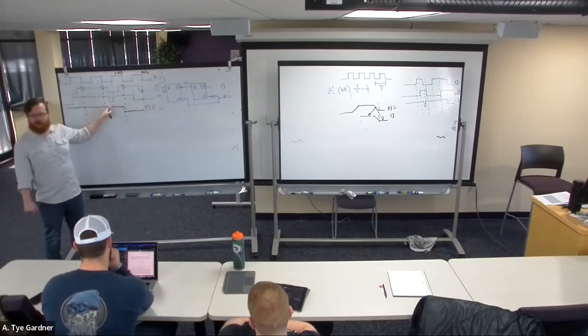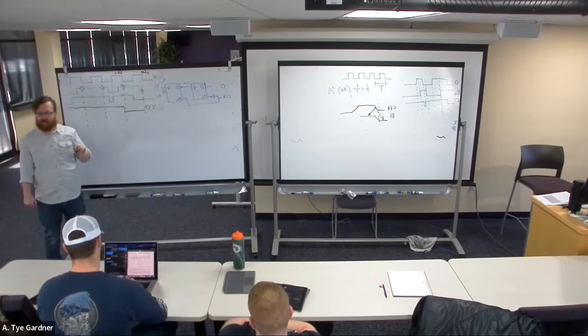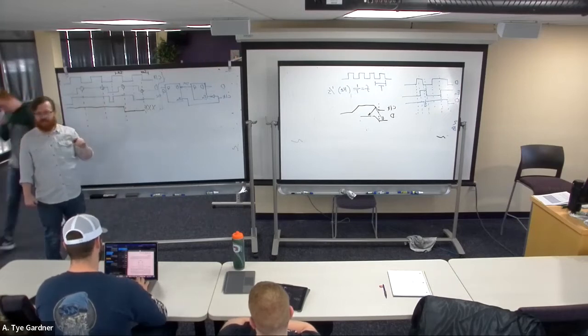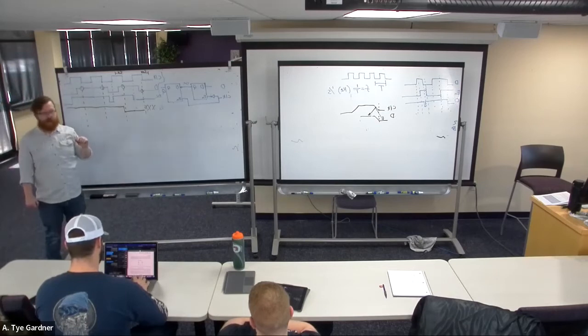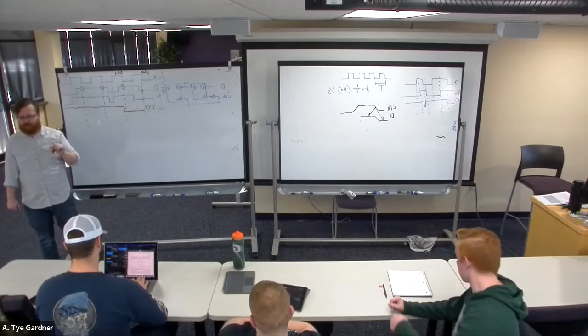It completely ignores any weird little blips that are happening to the D input signal. That's the nice thing with these D flip-flops: now I have combined 2 D latches to build a D flip-flop that will react only to the rising edge.